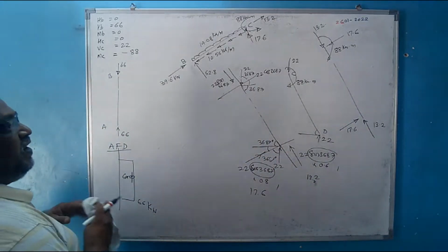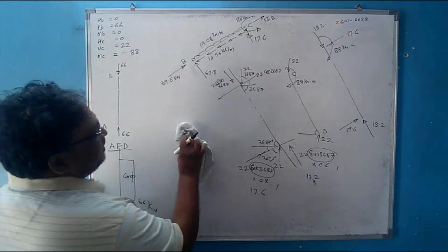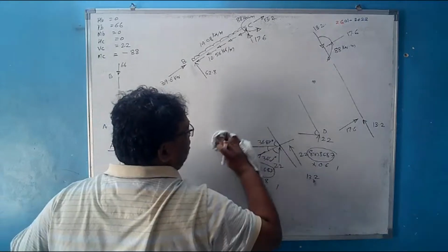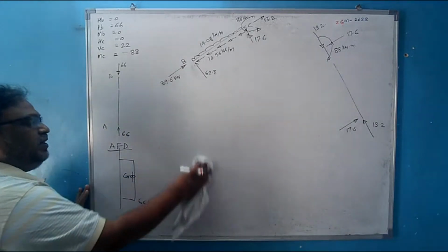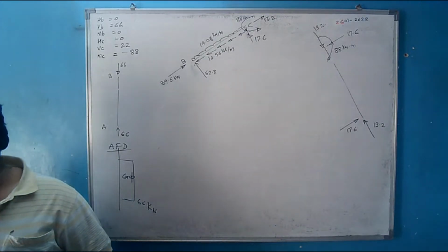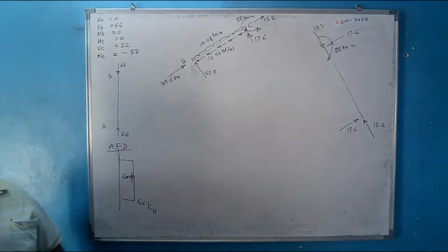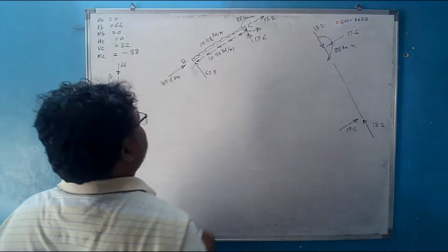We have got the free body diagram for the other two members also, where the forces were acting inclined. जहां पर भी कोई distributed force आता है inclined member पे, तो काम थोड़ा और बढ़ जाता है. Wherever there is inclined member, हमको forces को along and perpendicular resolve करना पड़ता है. Right? Now sketch the shear force and bending moment diagram for this part.